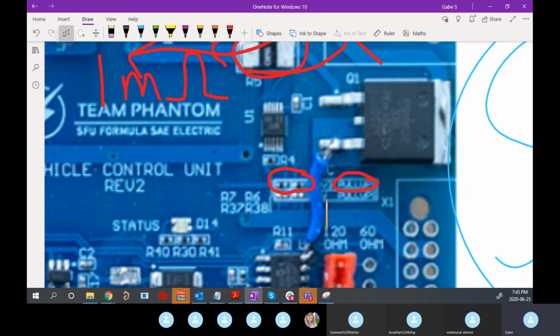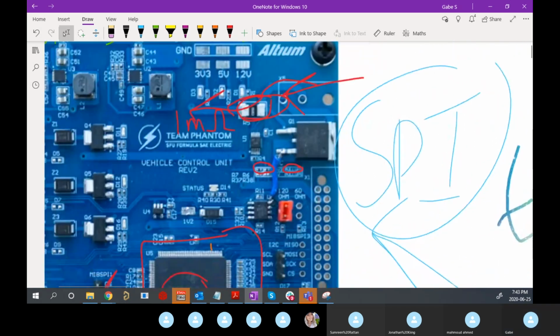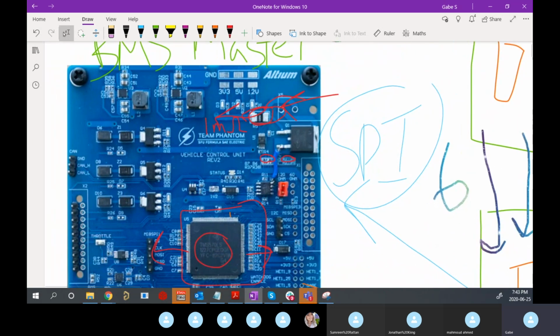A good tip whenever you're laying out a board like this is that these communication protocols, especially when you do it for the first time, go wrong a lot. Like you can imagine you write the code for it to talk, you hit run, and then you just don't get anything back. You're like, all right, what are the 100 different possible errors that could have occurred? So what we do is we use something called the logic analyzer.